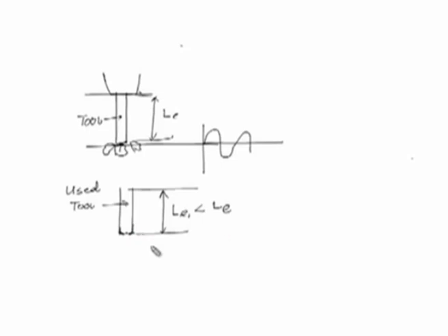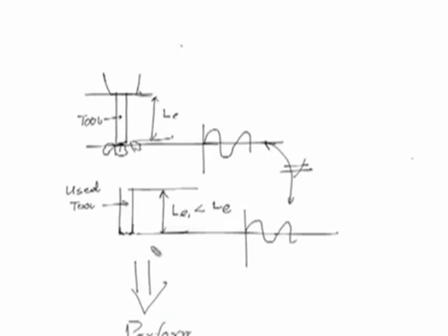Then the vibration characteristics and the energy available here will be different. So, this and this will never be the same, and therefore, this will ultimately affect the process performance. In fact, it will be reduced. Thus, it is very important that the tool length or the tool dimension remains the same while working with USM.